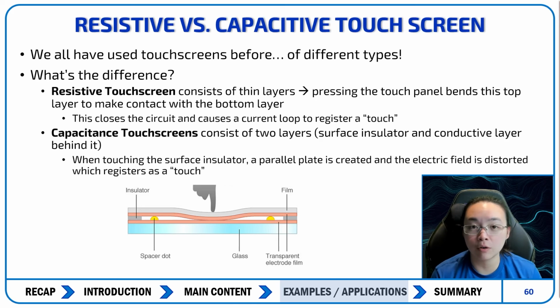So you can use your finger, you can use a stylus, you can even use any hard object to just push it. So what I would say is that if you're choosing between a resistive and a capacitive touch screen, a resistive touch screen is more effective for simple panel controls like the GPS control panel in a car, other keypad replacement applications, or in applications where you have to use a glove.